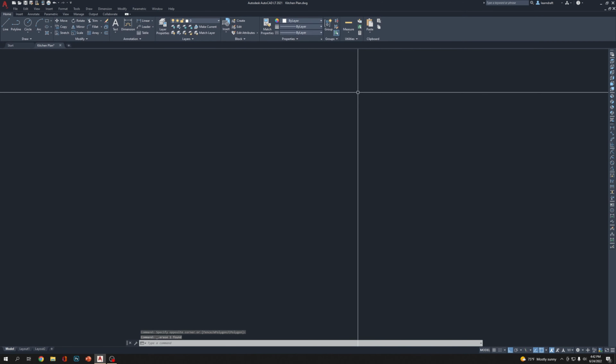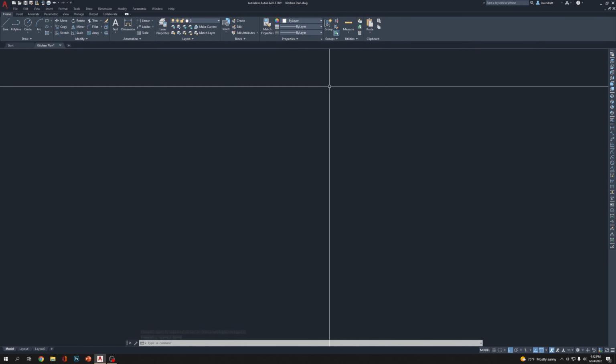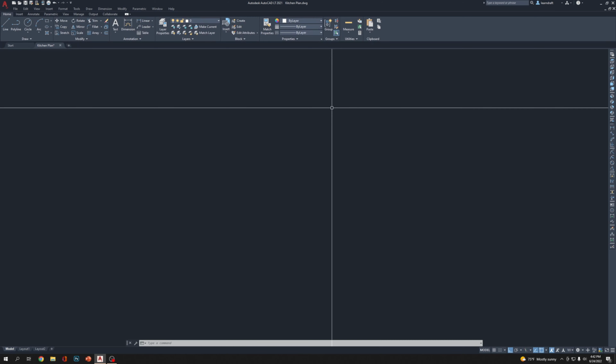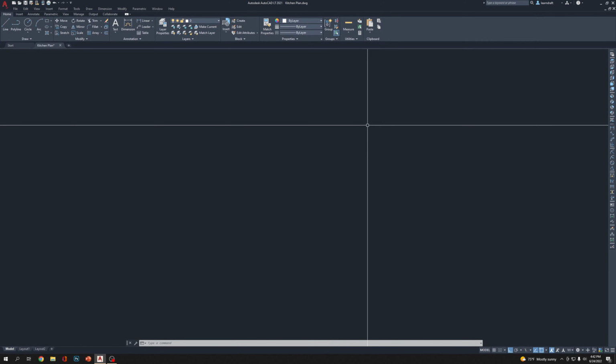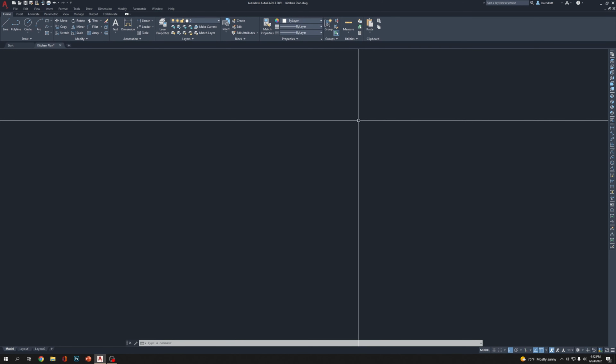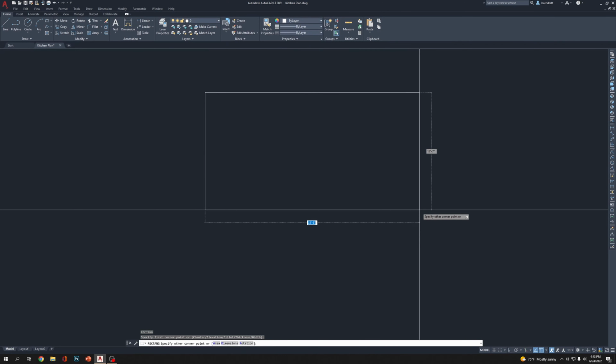Hello and welcome guys. Today we are going to draw a kitchen. Normally kitchens come in small, long, and wide sizes. Our kitchen is mid-size. I'm drawing a rectangle. REC, enter, click, D, enter, which is actually 15 feet long and only 9 feet wide.